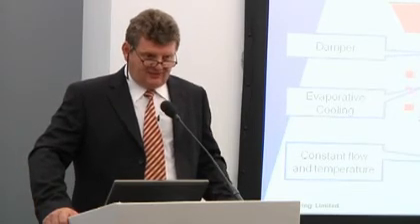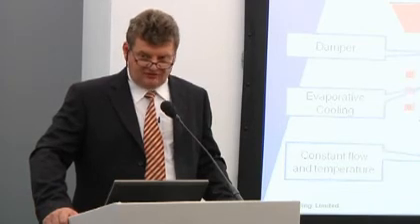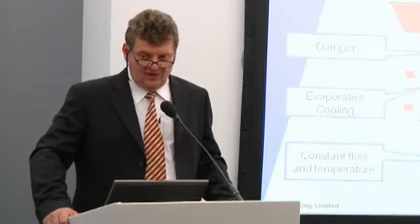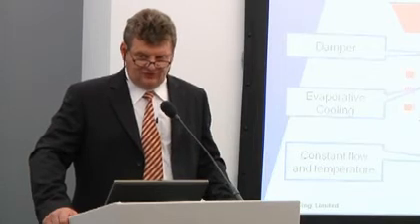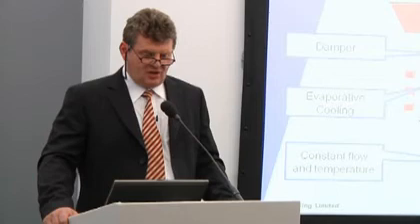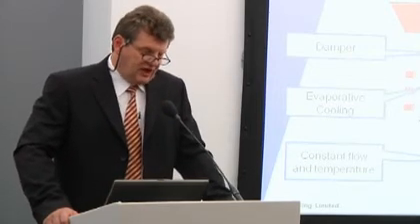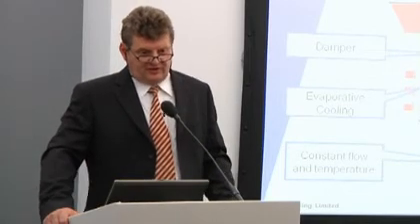For 90% of the time we will be running on a fresh air system, just using the hot air to warm the ambient air up to give us compliant conditions going forward, typically about 20 degrees centigrade. Just as a slight aside, when we commissioned M247, we started with a set point of 20 degrees centigrade.